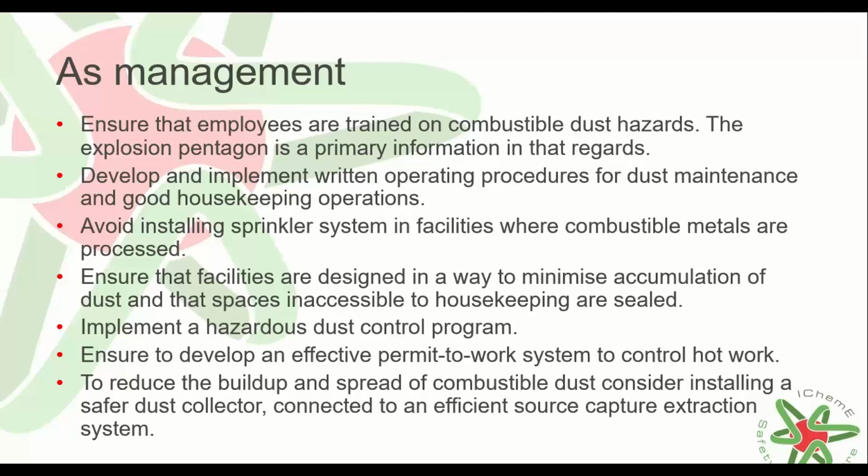For example, segregating dust producing operations, sealing walls, ceilings, and using electrical equipment suitable for explosive atmospheres. Implement a hazardous dust control program that includes dust inspection, testing, and also housekeeping. Ensure to develop an effective permit to work system to control hot work, welding, and so on in the facility.